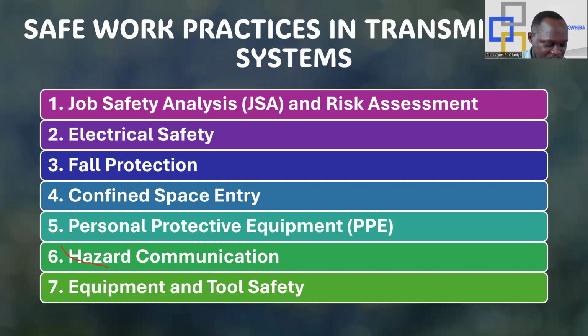Okay, 15 meters away from the transmission line. This will help us to actually know the distance we are expected to keep. Okay, thank you. For 132 kV, it is 15 meters, while for 330 kV it is a 25-meter distance. The reason for this distance is safety, because when there is an issue that needs to be addressed, or maybe a hazard, or an incident that happens, you never can tell. All these things have a lot of dangers posed towards us.